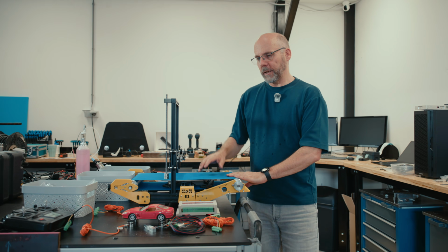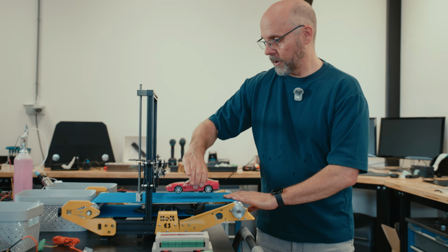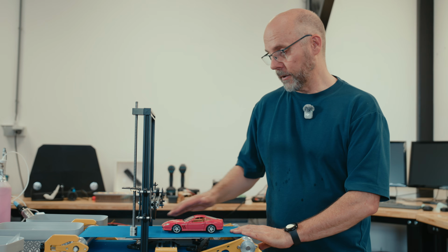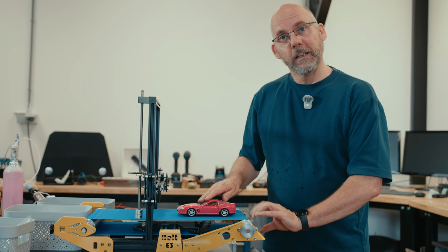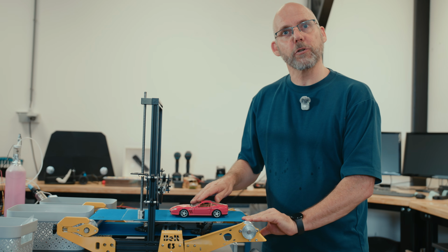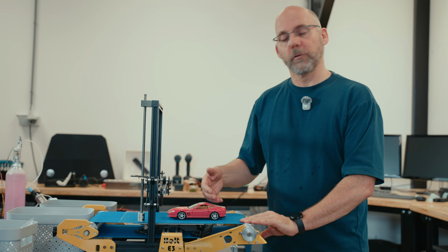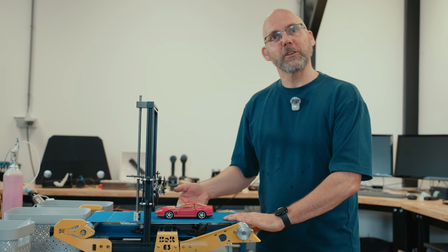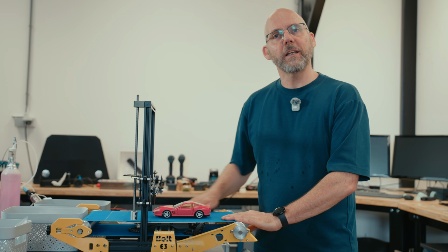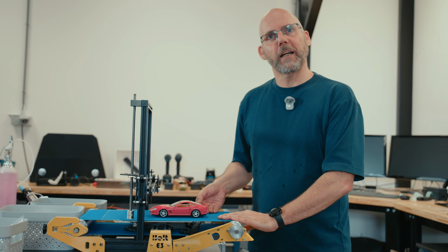So what we can do on here is put the car on the treadmill, have the wind come from the front and rotate the treadmill while the wind is going, so match the speed. So the car will have the full sensation as if it's driving. And in that way we can actually show what happens when the wind is also pulled along by the rolling road.